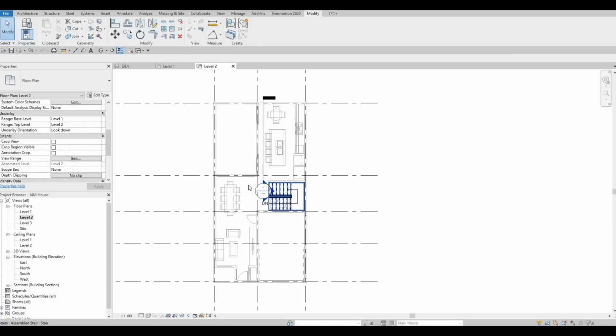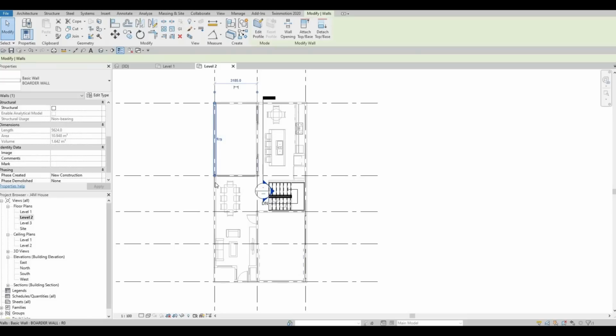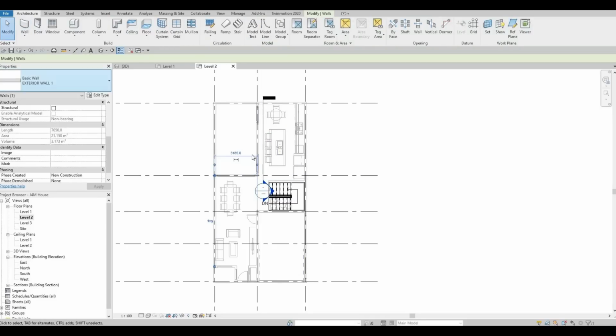So for me, I want to turn that on because I could select, for example, this exterior wall or the border wall or the exterior wall, and then I could use CS in order to add it instantly here. I don't need to look for the wall right here and so forth. So it's an easy way to add all the things that you already added.